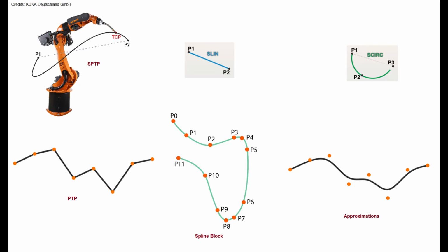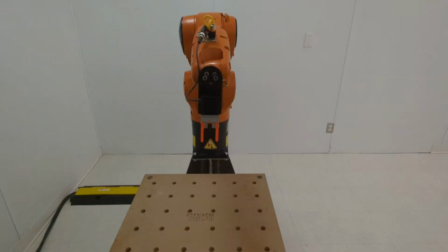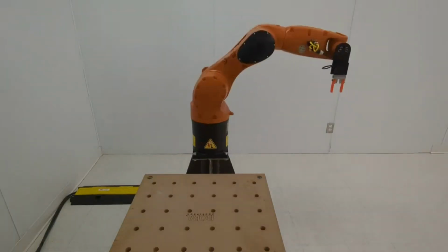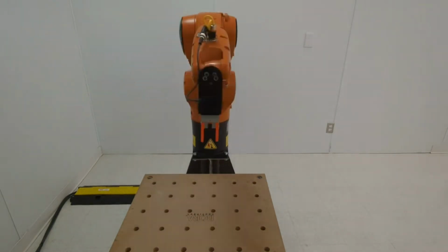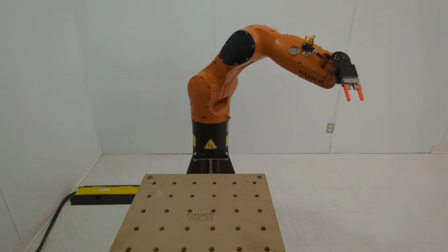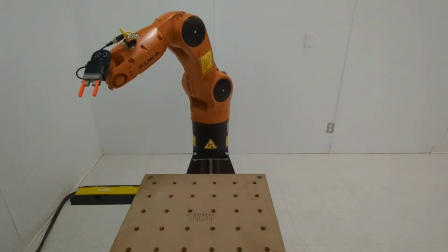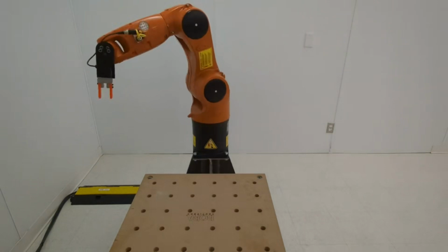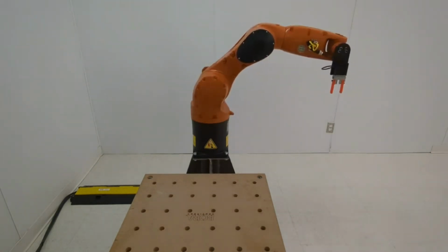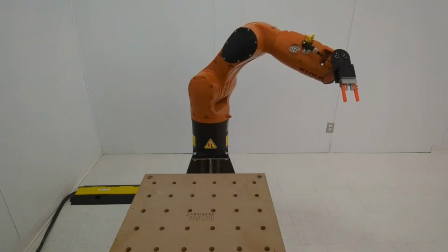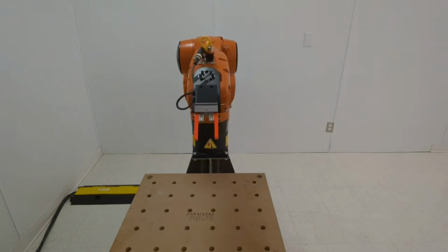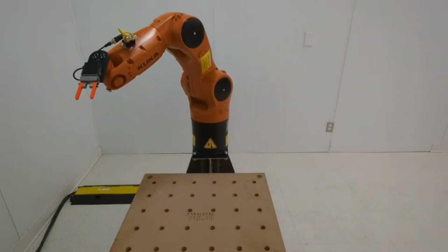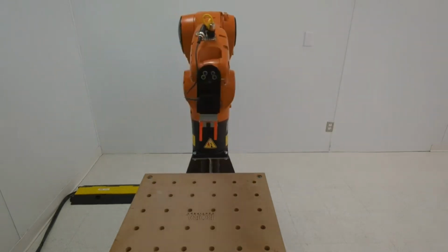The first demonstration shows different types of motion profiles that the robot is capable of executing. Notice that the robot dynamically adjusts the orientation of the object, which is the tool tip, in some motion profiles. The velocity of the arm is also changing based on the motion profiles. This ensures that the robot system is safe and reaches every programmed point in space with the given constraints.